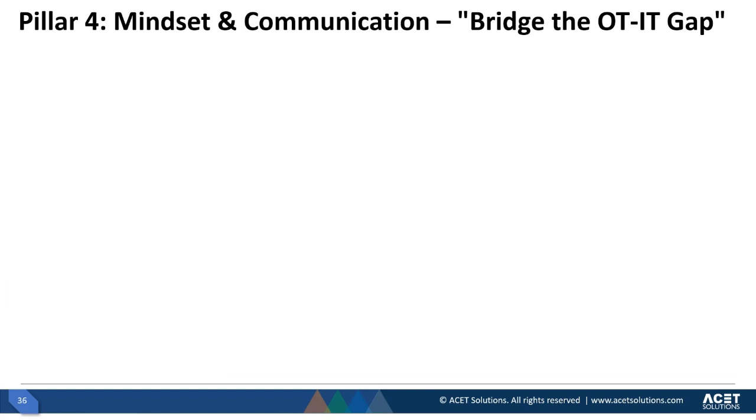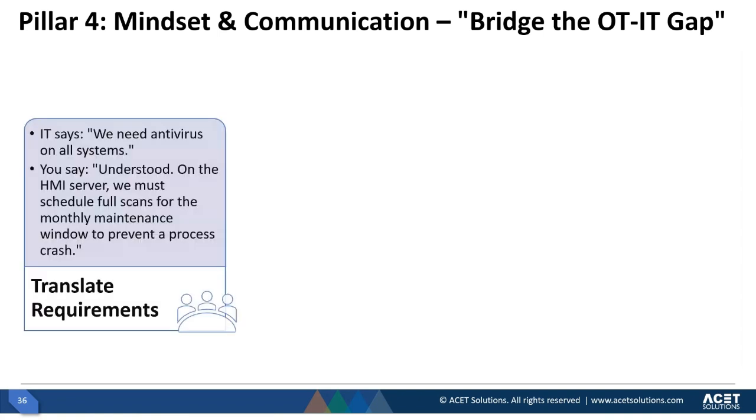If, let's say, we from the IT side say, okay, we need antivirus on all the systems, you need to understand this in a good way, and you need to tell the IT team that on the HMI server, the full scan has to be done in the maintenance window, not in a live running environment, so that the process does not crash.